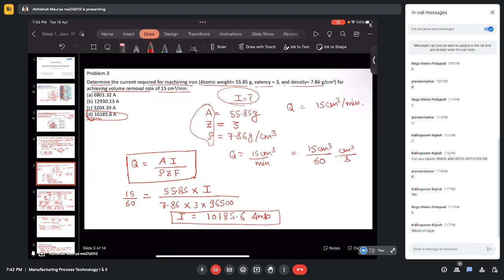And in electrode discharge machining, the material is getting removed because of the discharge taking place, and discharge is nothing but a spark where material locally gets melted, and because of the shock waves it gets removed.